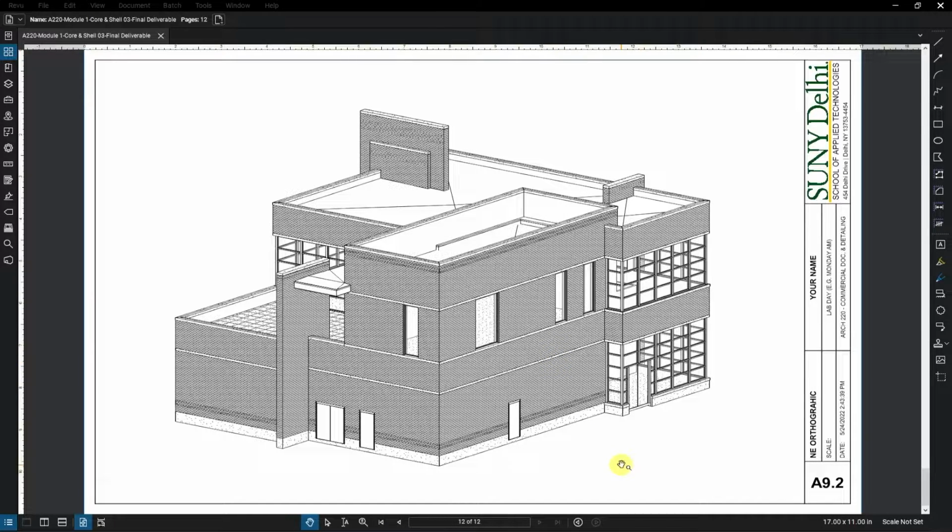There's several ways to do this in Revit, but the most applicable to our model will be using what Revit calls wall sweeps, which are embedded into our wall types. Essentially, wall sweeps are two-dimensional profiles or shapes that are swept or extruded horizontally or vertically through a wall's length or height. In our case, our sweeps will be horizontal, as you can see here.